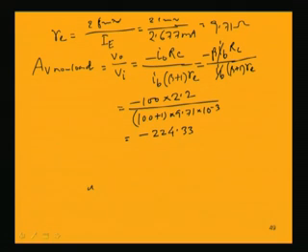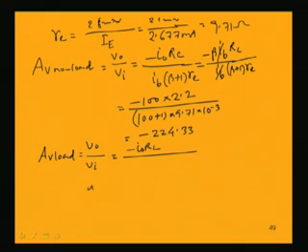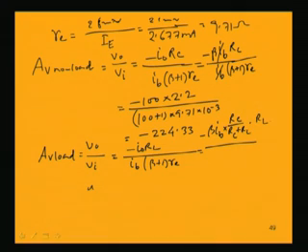If I consider load, so this value of V naught by Vi will be minus I naught into RL by denominator will be same. So, finally, I naught can be written as beta IB into that part of the current which flows through RL, and that is beta times of IB into RC by RC parallel RL into RL by IB into beta plus 1 RE.